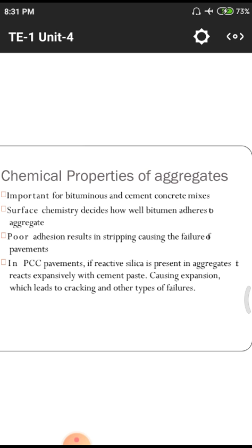Otherwise those will lead to active cracks; passive cracks are there also. Active means if a small crack is developed on the road, it will lead to a long crack simply by passing traffic. Whenever the vehicle load is applied on the crack, it elongates day by day. It will lead to a huge amount of lengthy cracks. So we need to arrest those kinds of cracks when we observe them on the road surface.